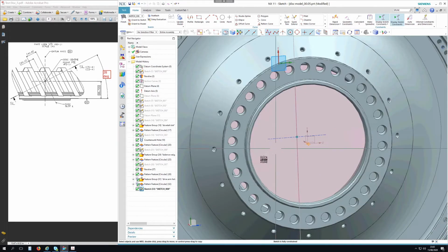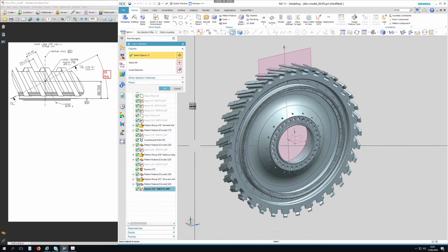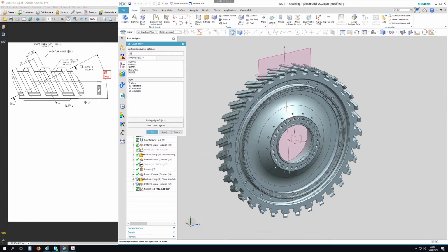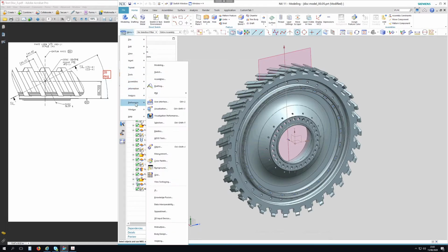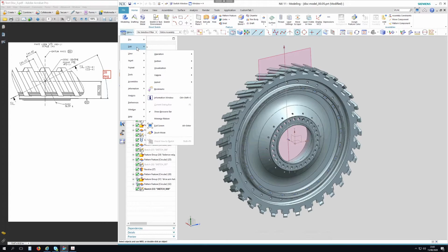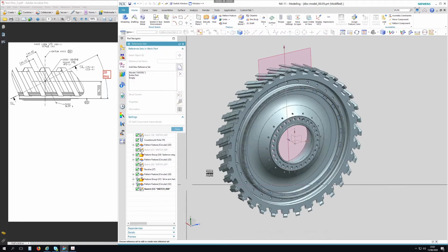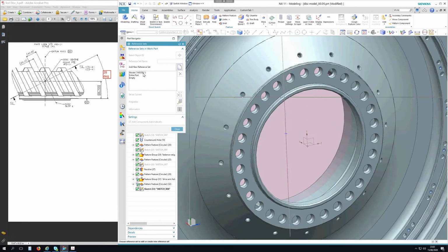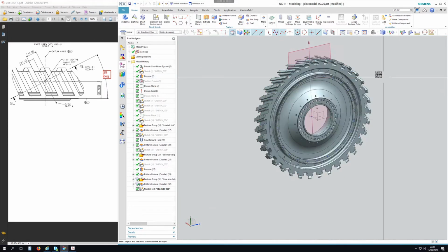So now I need to put that point on the right model reference set. So let's go finish sketch. Let's move it to a layer. Let's put it on layer 70. And let's go format reference sets, model. Let's pick that point. Yep, that's it.